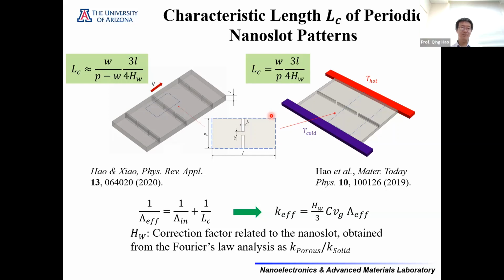And also I mentioned the cooling application, possible cooling using nanoporous silicon thin film, because it has a very large surface volume ratio, right? So you can dissipate more heat out of the device. And right now we know that device cooling is the major bottleneck for the high power electronics, right? So there are a lot of things we can think about. And beyond that, thermal electrics is still useful for certain device cooling applications, and we can integrate those nanofilms with other silicon devices, because they could be fabricated from the same device layer, right? And that could be another consideration. And mostly we consider cooling protection.